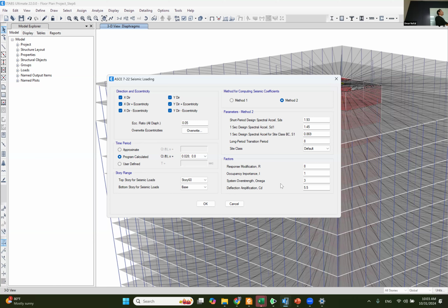That's actually what causes the building to have torsion. Do you guys remember when we said if you have a building and this building is held from here and a force hits, it's gonna rotate like this? Why is it rotating like this? Because the force is hitting at the center of mass and it's rotating about the center of inertia. But if you have a shear wall here, these two are gonna be the same, right?